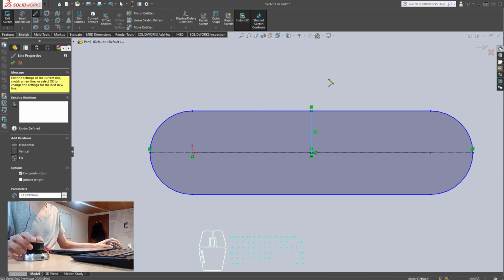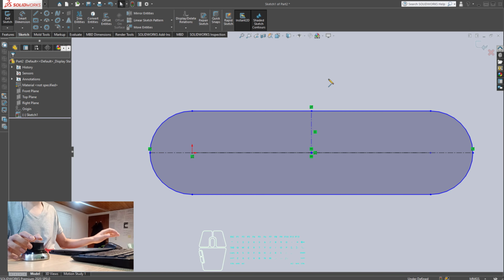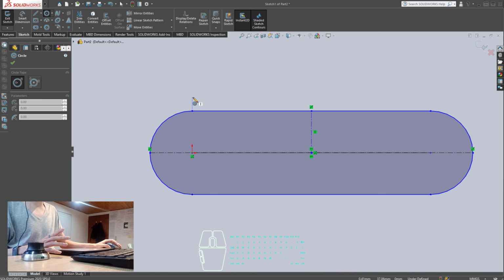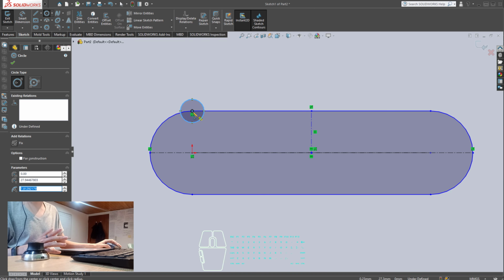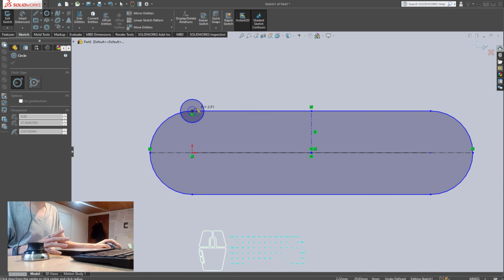Why is that? Because we have on the engineering drawing that we will check later, that every quarter of the part is exactly the same as the other. It is just mirrored, right? So we will take that property to take advantage of the time and be as fast as we can creating this 3D model.